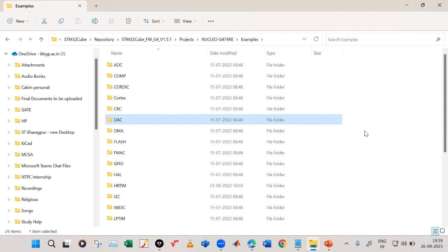Now if you want an FPGA, you have to buy the FPGA kit. Then for ADC and DAC also, you have to make a signal conditioning board and interface it to your FPGA. All that headache you have to do. But over here, we are using the internal ADCs, internal DACs, etc. So this is a more effective and useful thing which you can do.